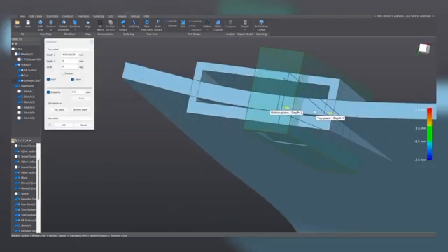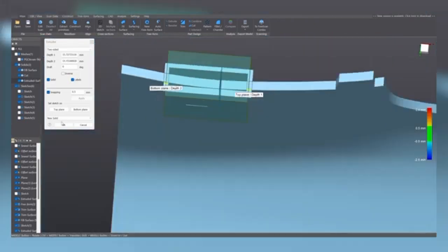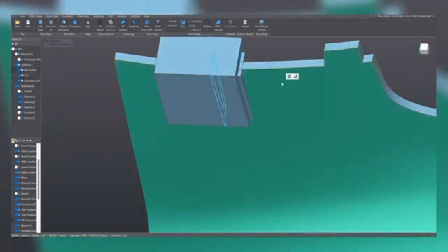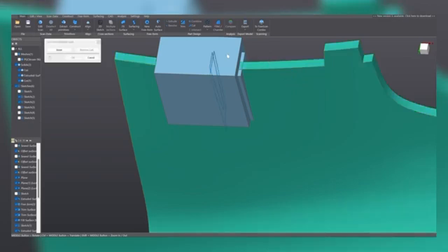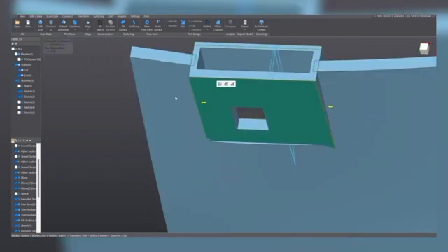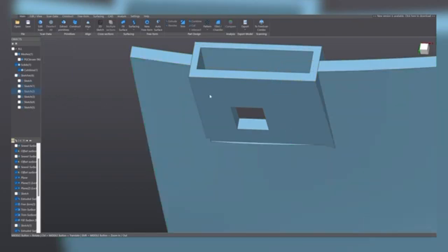Select the rectangle, and let's extrude it until it goes here inside the walls of the new solid that we have designed. And likewise here. New solid is again selected. Click on OK. And now we choose this solid, and we tell the software that we want to cut this solid with this one. There we go. Now we are good to select both solids with the Control key and combine them together. Let's hide these sketches.